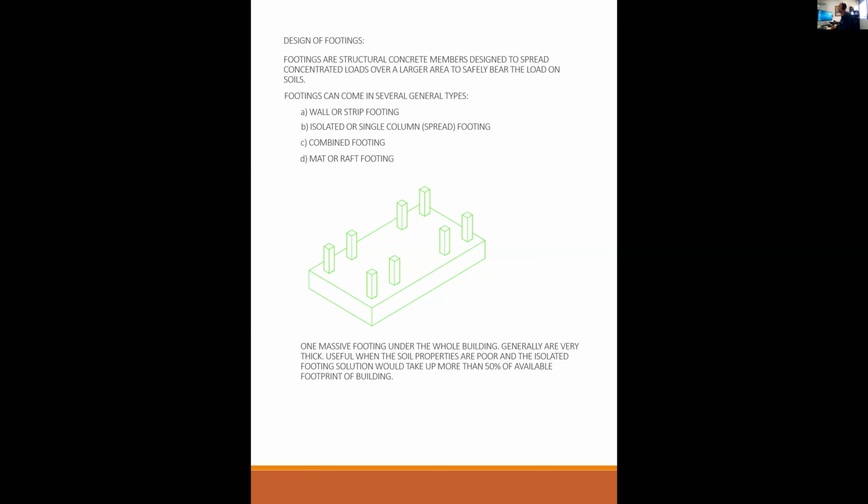Like if you're doing a light duty warehouse, it's 4 inches. If you've got forklifts, it may be 5 inches. If you're doing truck loading, maybe 6 or 8 inches, just various guidelines. But that's totally different than a mat foundation where you actually design for shears and moments and things like that.